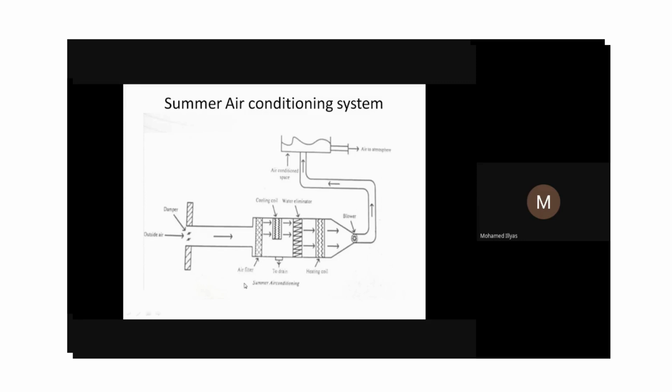The vapor will condense. We call it the dew point temperature. The pressure is increasing, and the entropy remains constant. Vertical line, so entropy remains constant. The enthalpy is also increasing here. The air passing through our cooling coil, process 2 to 3, will be cooled till the dew point temperature.